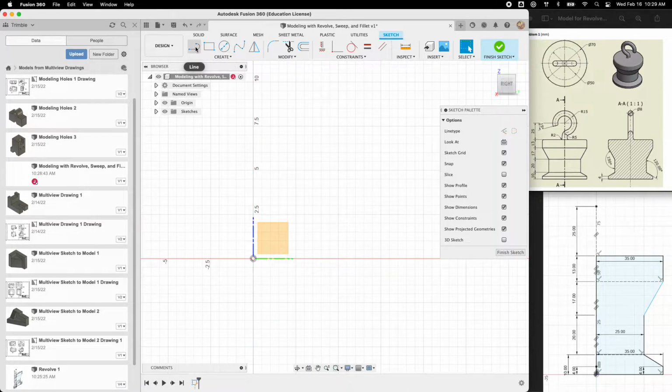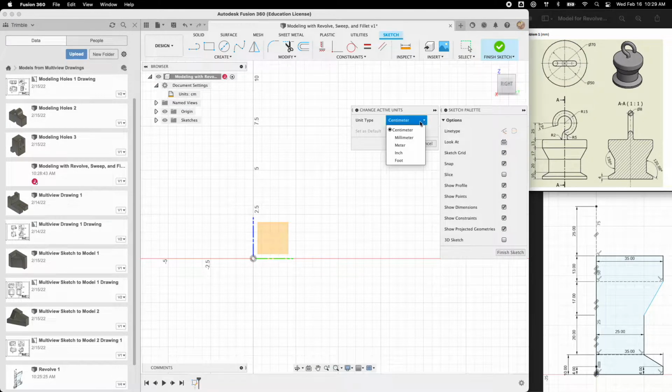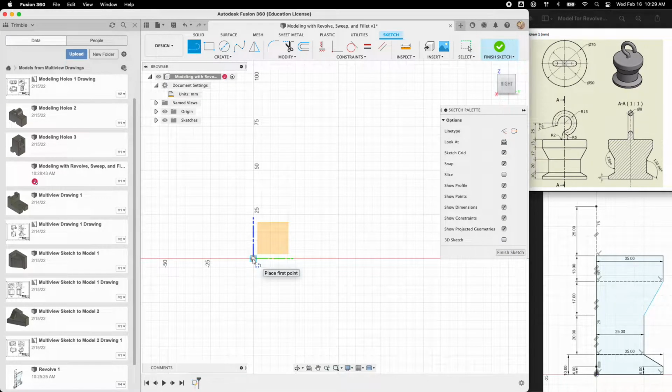the vertical axis. So to start with, I'm going to create some lines, and I'm going to look at my drawing on the right and create a series of short lines at the distances that are measured here. I'm going to start with one that is 10 units tall. The first thing you'll notice, I'm going to hit escape actually. This is in millimeters. So I'm going to go to document settings, and today I'm going to be in millimeters. I may not set that as default because I like centimeters more, but this one's in millimeters.